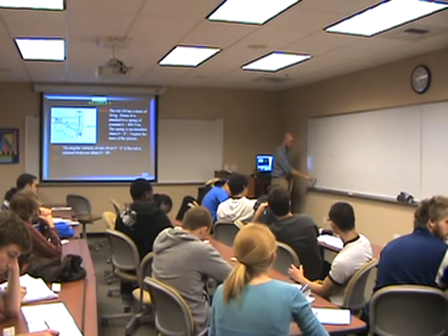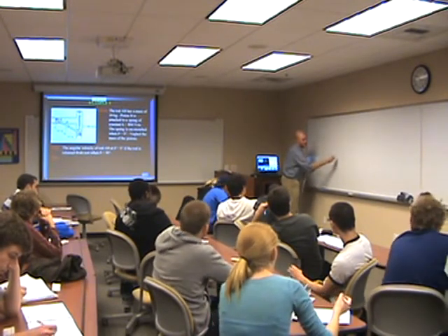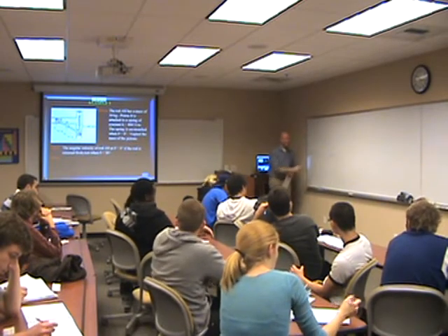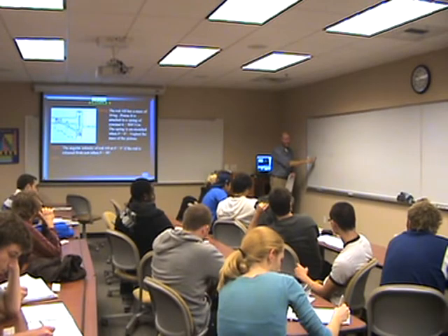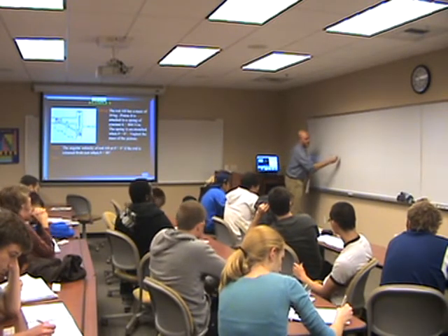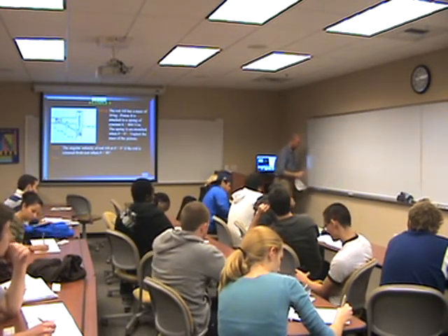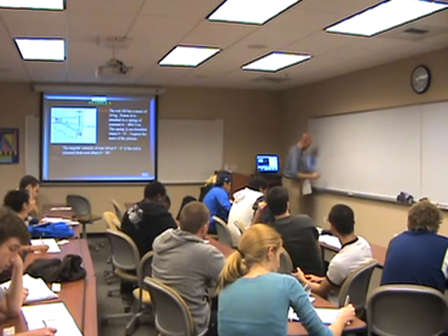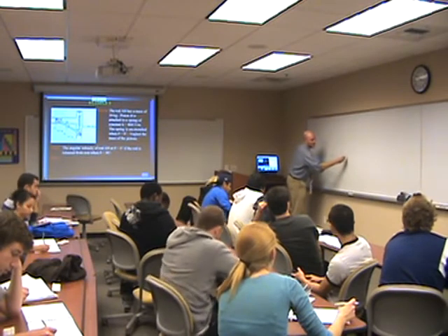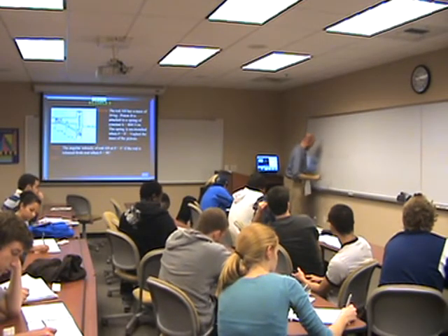And that's our velocity at our center of gravity, and then we need to square that. That's 1/2 m v_CG squared plus 1/2 I_CG, which is 1/12 mL squared. The mass is 10 kg.